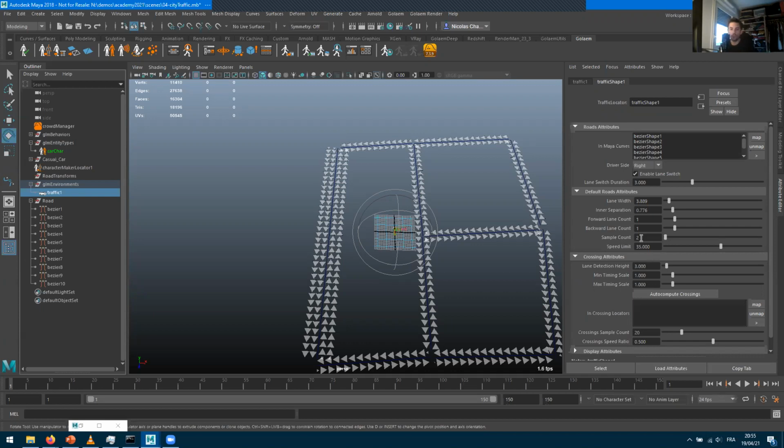If you have curvy roads, you just need to decide, either per curve or on your overall system, how many samples you'd like to take. And we're going to approximate your curve with the right sampling number. So yeah, that's the right way to do this. And if you've got bridges and so on and so forth, no problem with that. You'll have overlapping curves amongst each other and they will not detect themselves as crossings.